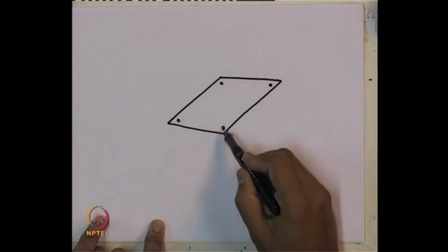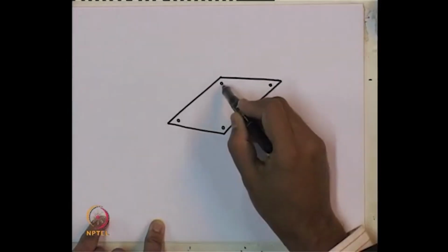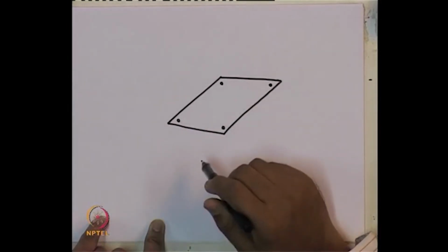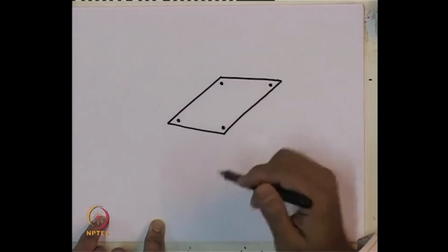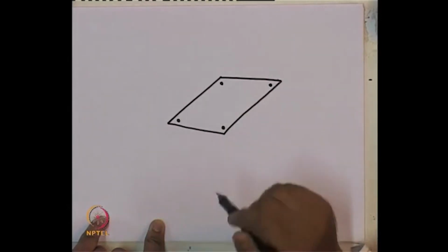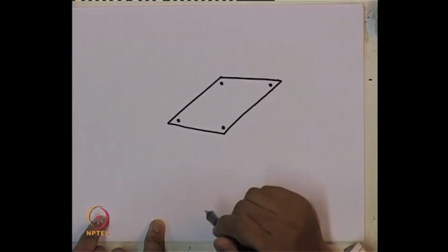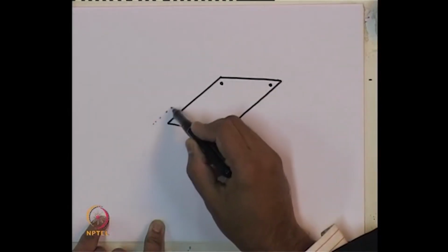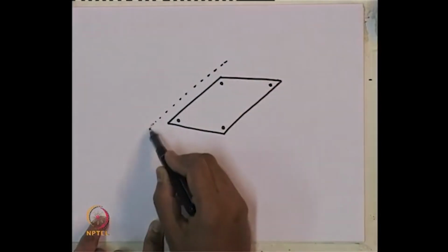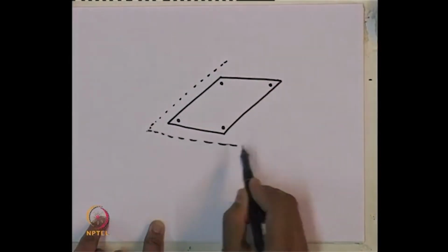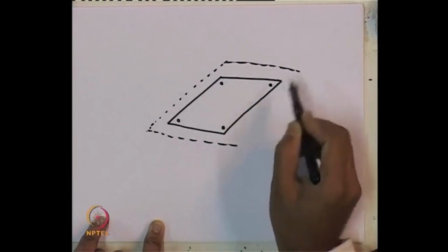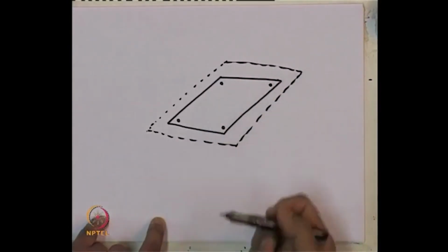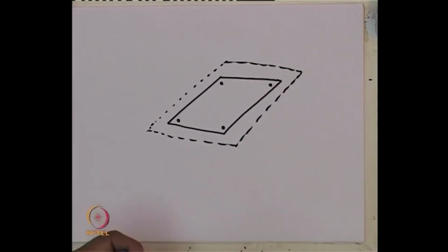Through these points we will bolt or connect the base plate, mostly the steel type of plate, to the concrete block type of foundation. And for that purpose, the area of the block which we are providing should be bigger than that of the base plate, otherwise we cannot fix them, of course.